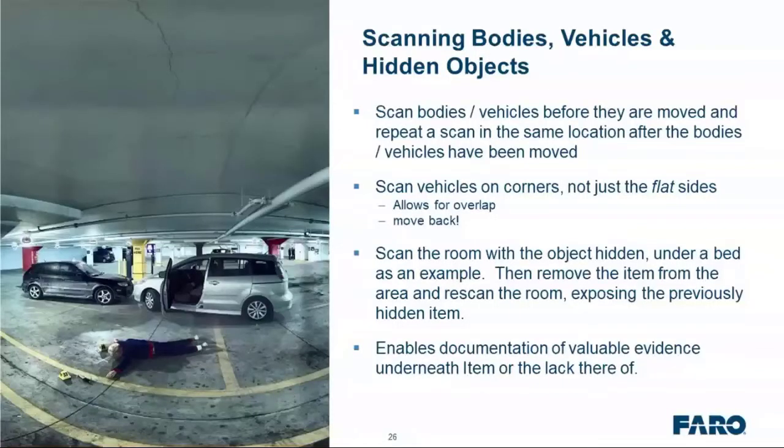The next topic we're going to get into is scanning indoor, outdoor, and in poor lighting conditions. So we have scan resolution guidelines for outdoor versus indoor scanning. When it comes to scanning indoors and outdoors, if we're scanning in a smaller space, a lower resolution can be used since there will be significant overlap. When we're in these small areas, especially crime scene, we tend to overlap quite a bit. So we have the benefit of using this lesser or lower resolution.